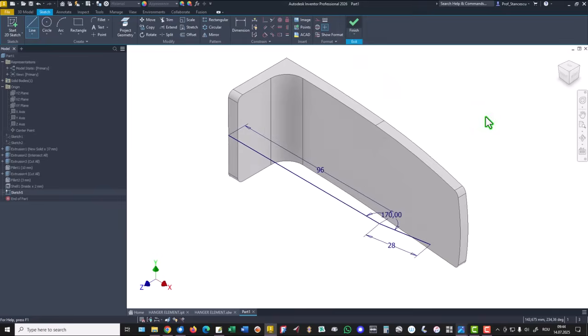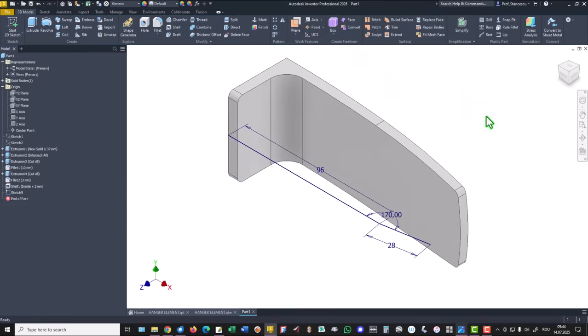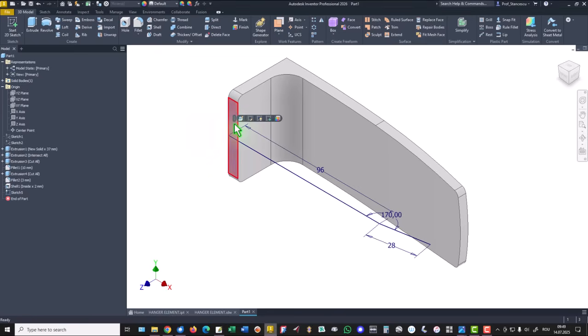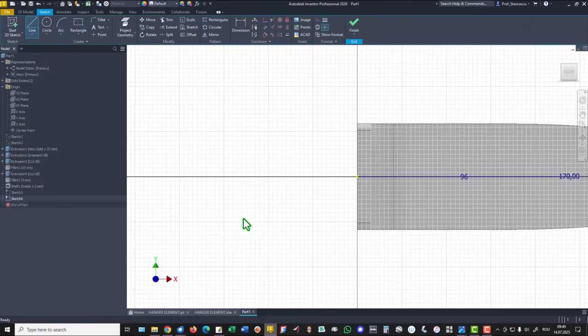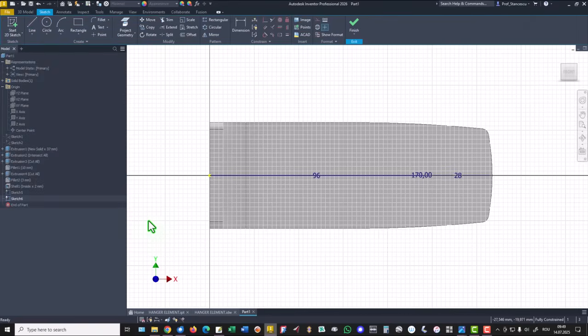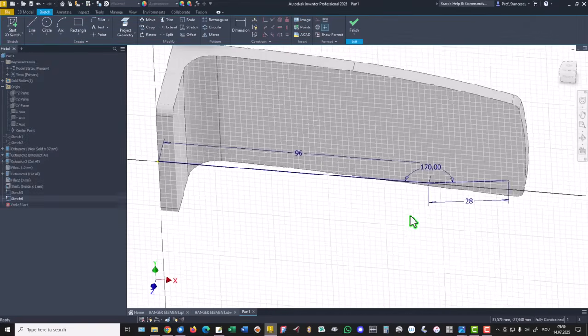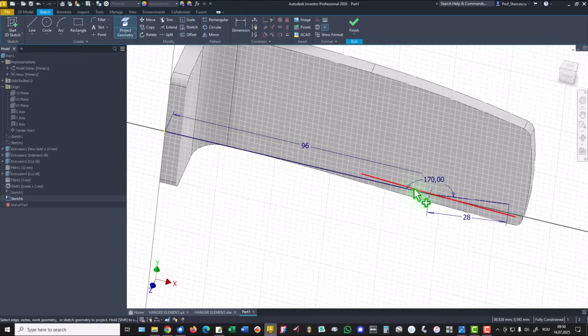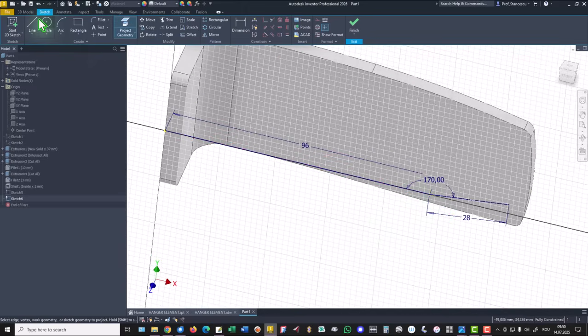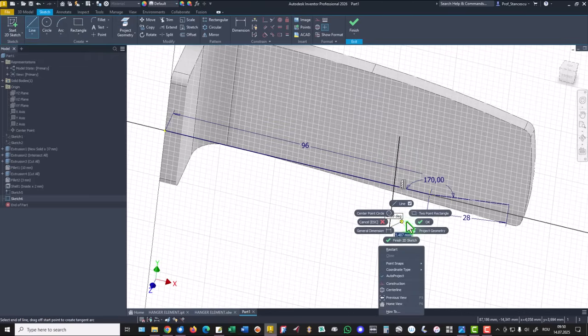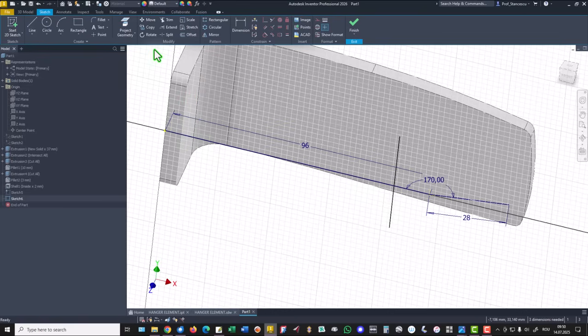Okay, this is the situation. We select this face for a new sketch, and we project only this point. We draw a vertical line, no matter what the length is, but it is important to place this midpoint coincident with this point. Finish sketch.